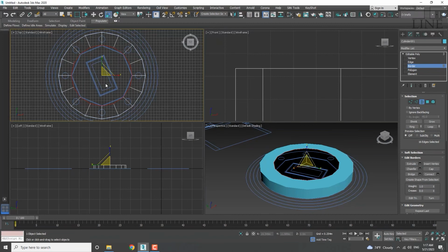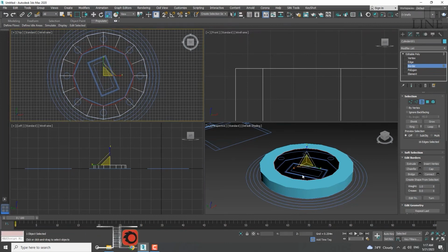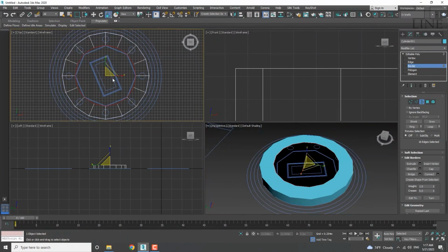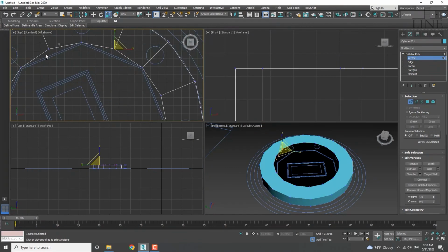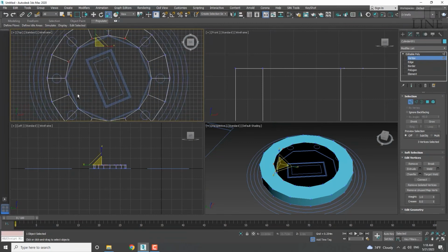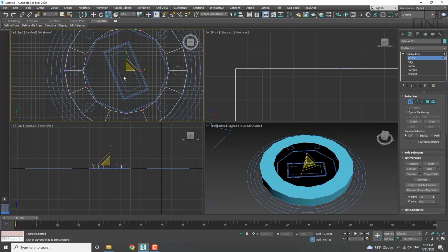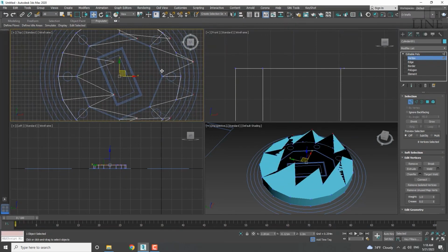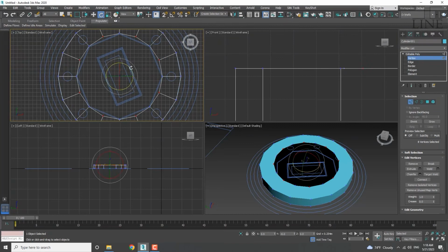Now, I have selected the border and brought it inwards. You see the result I got, what it is. I can press 1 or select vertex from here, and these vertices that are inside, you see, if I press W or press the mode, I can move these around. Or, as I said, rotate them. But now I want to use scale again to bring them inwards a bit, so they are on the line of my design. Very good. I need to bring them in a little more.